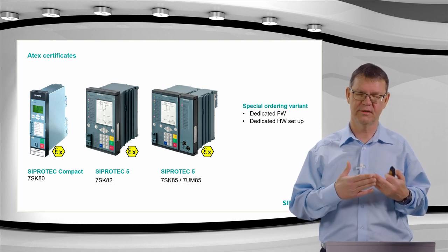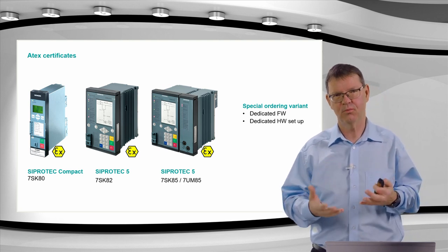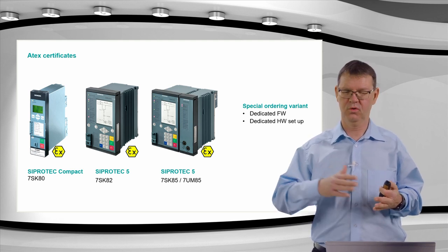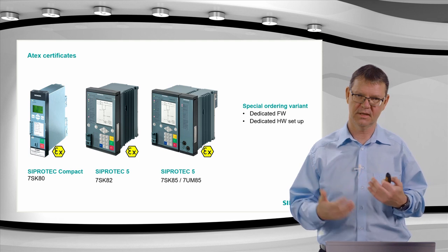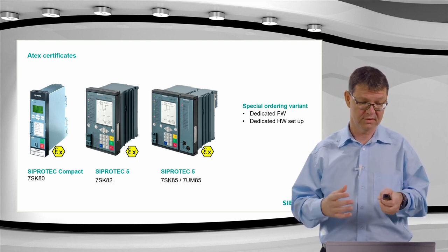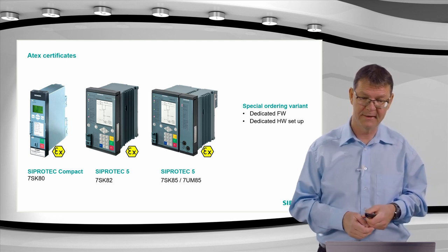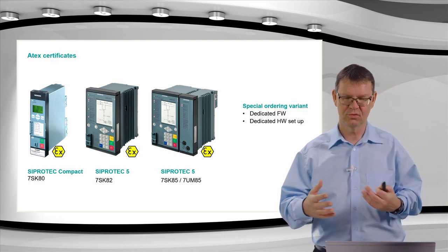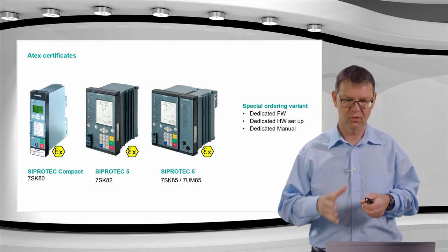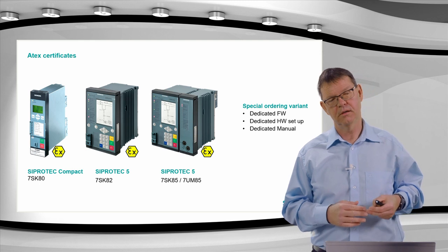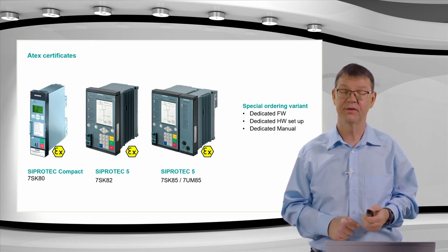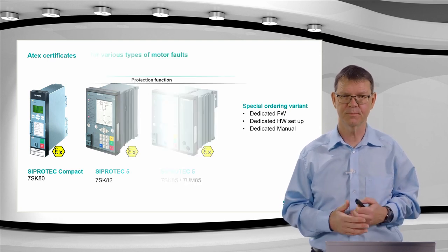And also if you change the hardware setup, and it's a hardware setup we have not tested and calculated and proved, then you are also falling out of that ATEX certification range. Therefore, you must just take the device as you can order it as a fixed box in that case. Although it's very interesting often to modify the hardware. And we have a dedicated manual that comes along with each of these devices, where some special measures are described, what you need to do so that you can run these devices under this ATEX qualification.